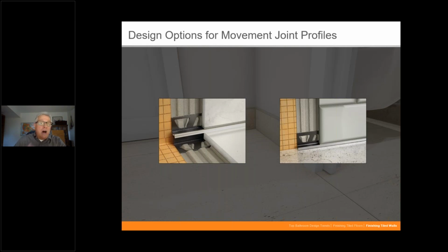It becomes the caulk joint. It is the joint between the two. It accommodates movement there at the changes in planes and for the floor to move in and out, and gives you that nice clean edge, and it's maintenance free. The other image used all the time, it's where we're not doing the countertops, just the backsplashes, for instance, and it's nice to introduce a profile like that to accommodate that movement.